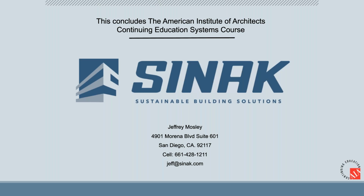A curing seal product, which would be your ASTM 1315 category, are membrane products that are designed to both cure and seal the product for up to 30 days. That gets you past your initial curing stage, and it starts to degrade as the drying phase starts to come into play. These are not permanent sealers. I've run into lots of instances on projects where I've got riser rooms or utility sections or even small warehouses where the owner gets upset because the concrete starts to dust, and they said, but I used a cure and seal. You have to understand that the word sealer has a broad range of definition. So that's the first thing.